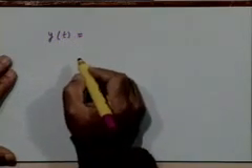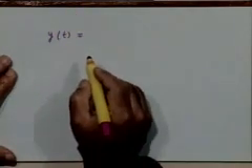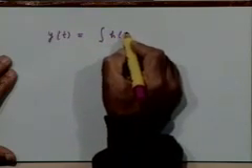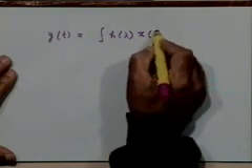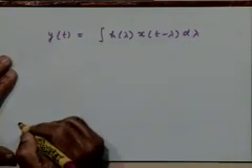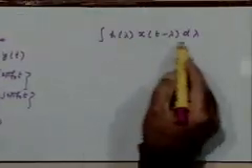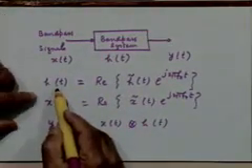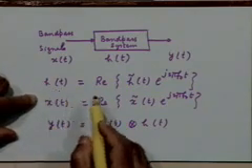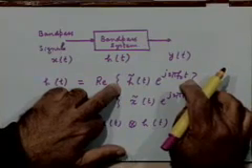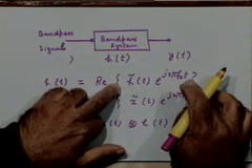So let's proceed. Let's use these two representations to find y of t, which is a convolution of h t with x t, which you can write like this, right? If I want to make use of this representation of h t and x t in this integral, how should I do it? I should substitute for h t this term plus its complex conjugate, half of that.